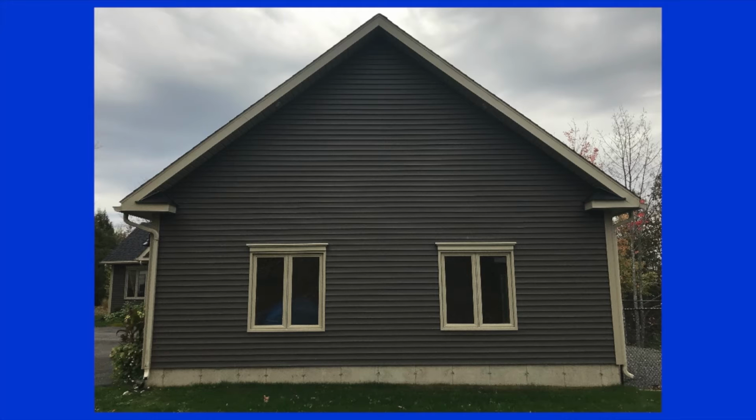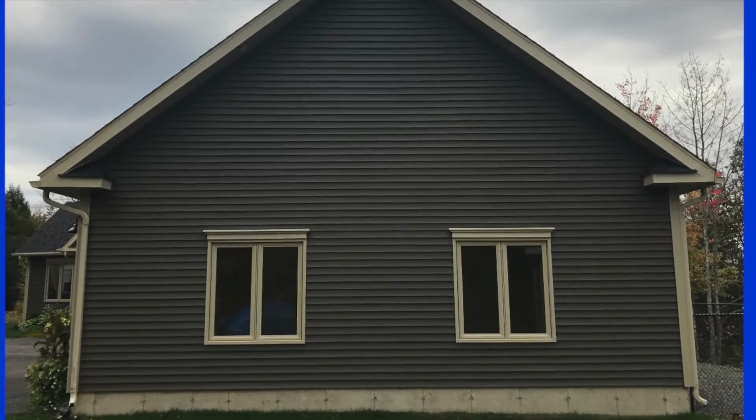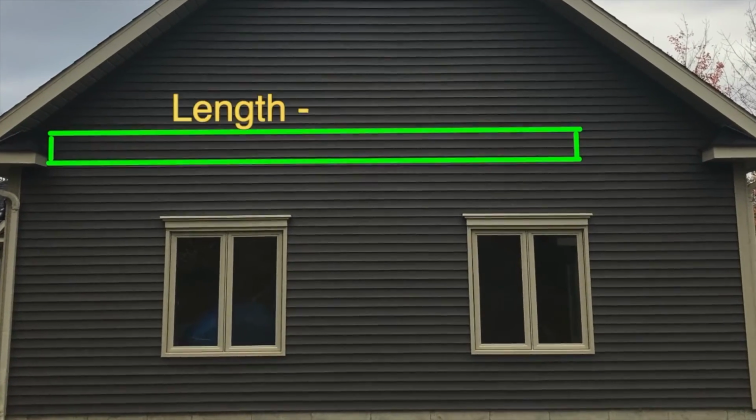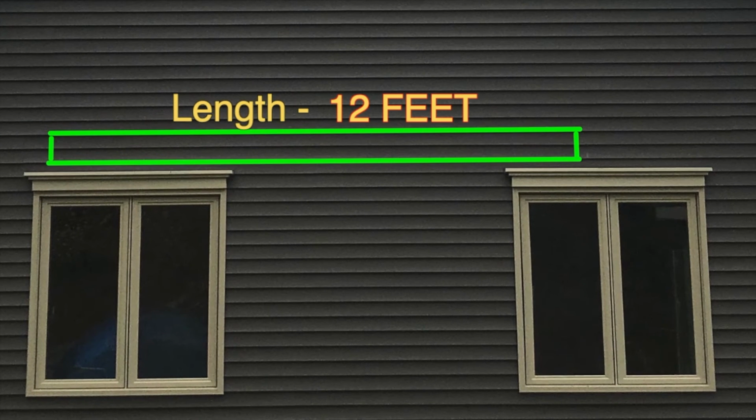Just like with the flooring calculation, we can determine how many pieces of vinyl siding will be needed for the job. To do so, what do we need to know first? Exactly! We need to know the size of a single piece of siding material. For the vinyl siding used on this house, each piece measures 12 feet in length and 8 inches in width. Pause the video here to see if you can figure out how many pieces of siding would be needed for this end of the house, and then come back and check your calculation.